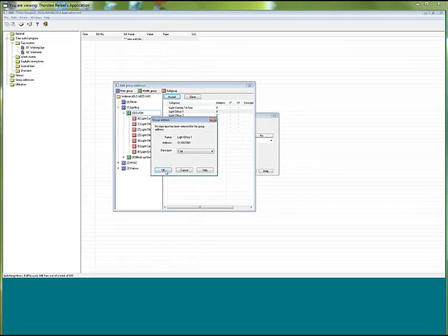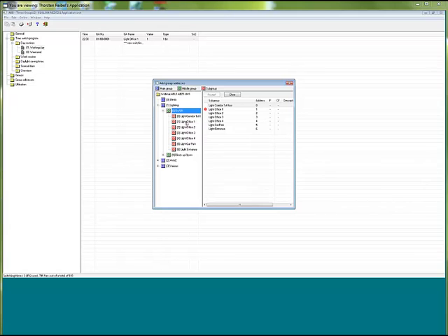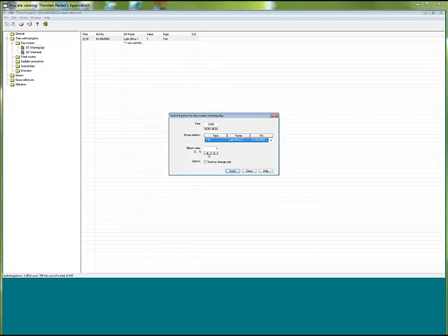Now you can confirm. At 10 o'clock in the evening, you operate light office 1 with which function, on or off is the option here. 1 is on, 0 is off. Up to you. Insert. And the first time function in the day routine working day has been set. Now you can say, okay, I need more. I need now at 11 o'clock another function, whatever it means, new group address. And I need now office number 2, accept, okay, but it should be switched off, insert, and close.